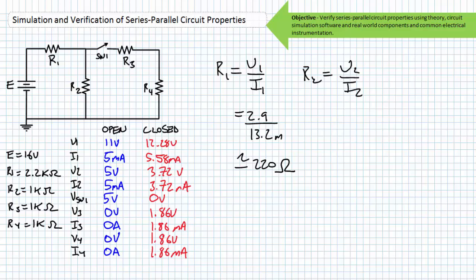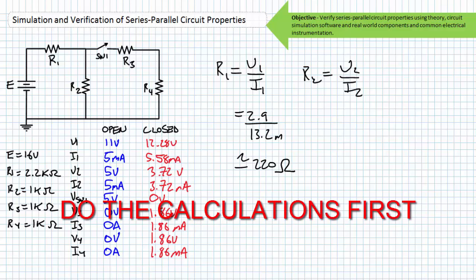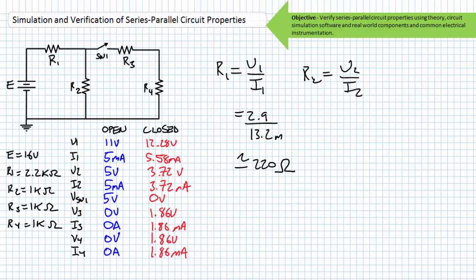Errors like this shouldn't happen. Good lab practices dictate you check your gear before you use it. Read the 4-band color code. Check each resistor with an ohm meter. Pick a good lab partner. Far more important than these simple recommended practices is your application of theory to these troubleshooting scenarios. Do the calculations first. Know what to expect. You can identify excursions and pinpoint the problem.